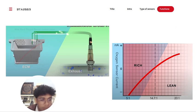Now, most catalytic converter equipped cars are going to have a minimum of two oxygen sensors. One is going to be before and one after the catalytic converter. The one before the catalytic converter is called the upstream oxygen sensor, and it's usually going to be right at the exhaust manifold or right behind it. It is used to see the exact air-fuel ratio at which the engine is running. The one after the catalytic converter is called the downstream sensor, and it is used to verify that the catalytic converter is properly doing its job.